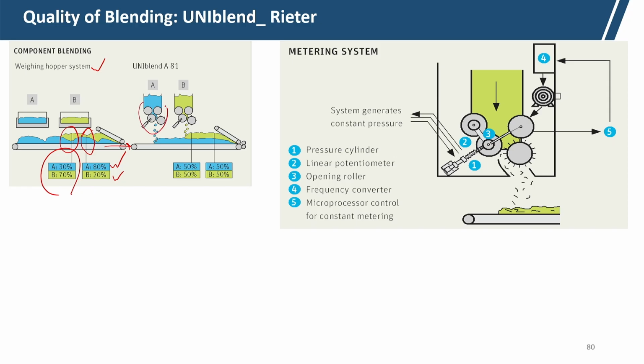fiber into smaller tufts, and after opening, the fibers are laid on the conveyor in a uniform, precise manner. Here you can see the layers are almost parallel, and the thickness variation of each layer is very minute, almost nil. That is how, if you want to achieve a 50-50 blend, we are achieving a 50-50% blend in every stage.